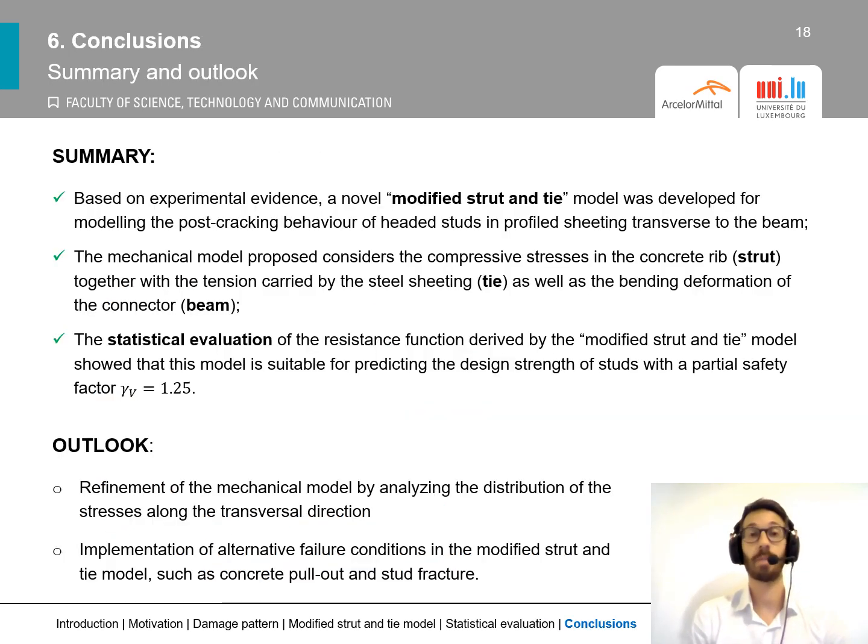So, based on experimental evidence, we can say that a novel modified strut and tie model was developed for modeling the post-cracking behavior of studs in profiled steel sheeting transverse to the beam. This model was also able to consider at the same time the compressive stresses in the concrete via struts, together with the tension carried by the steel sheeting via tie elements, as well as the bending deformation of the connector, which was replaced by beam elements.